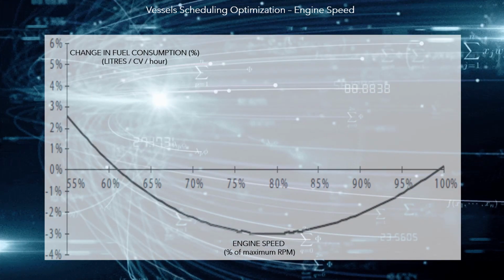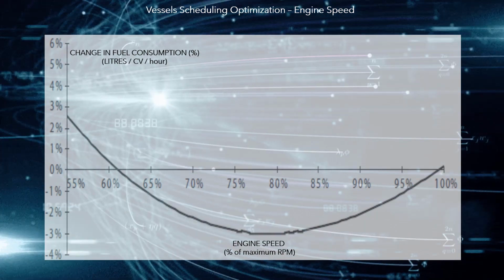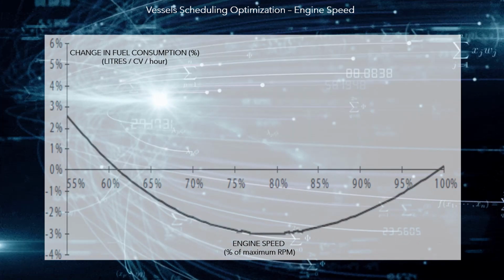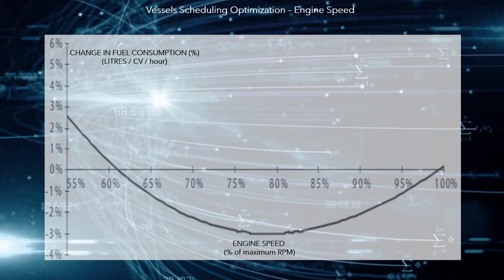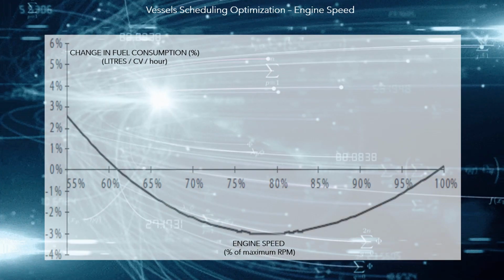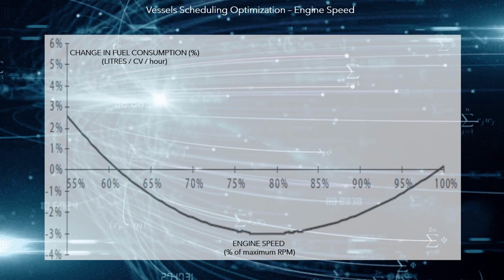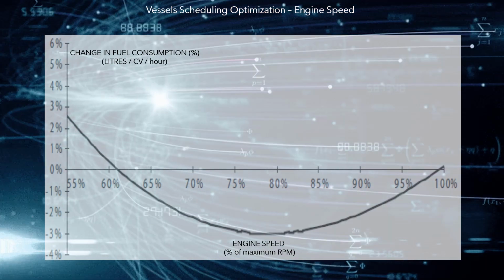Minimum cost RPMs are close to their maximum capacity, in figure 80%. From that point, as the speed of the vessel's engine moves away from this point, the amount of fuel consumed per unit of displacement increases. On the other hand, these curves change depending on the weight of the vessel.